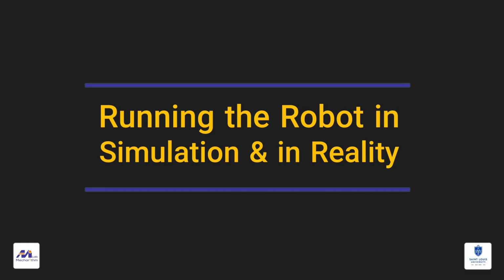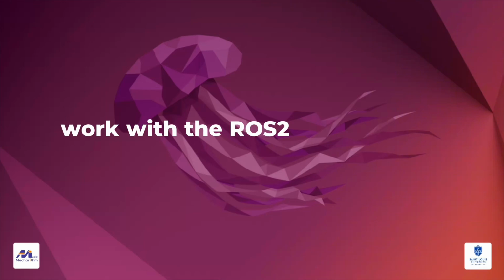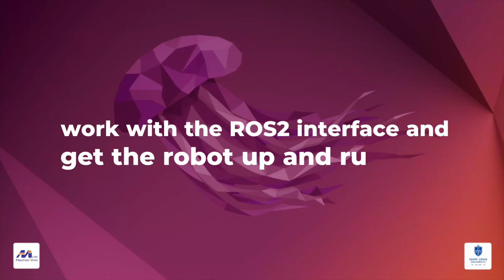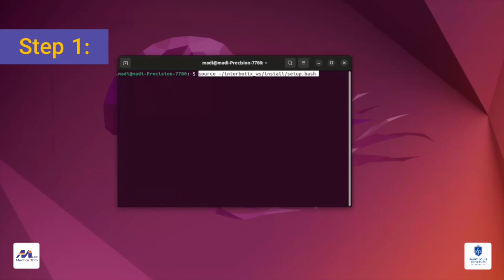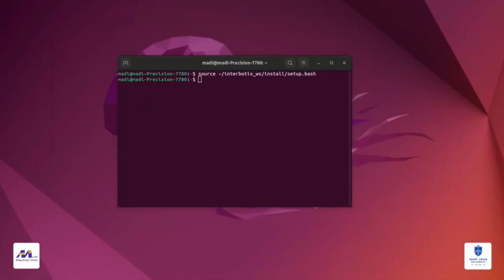In this part, you will learn how to work with the ROS2 interface and get the robot up and running. First, we need to source our workspace. This will set up the necessary environment variables and configurations for the packages installed in that workspace. When you run source, it executes the commands in the specified file, allowing you to access the packages and resources in the ROS workspace. Sourcing the workspace should be done in every new terminal to properly configure your ROS environment.